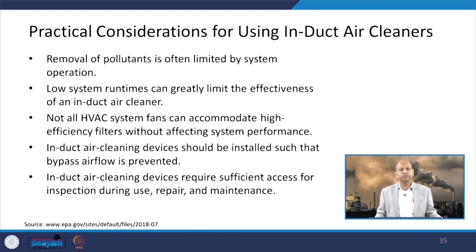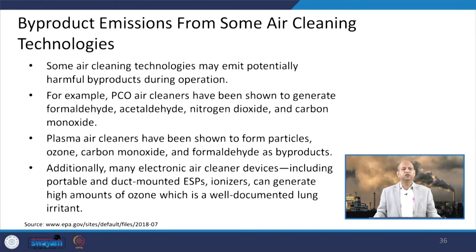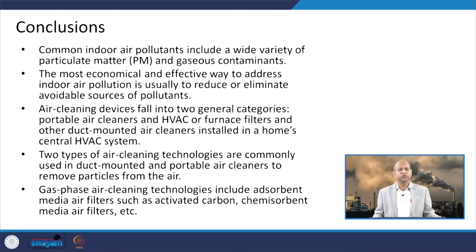Well, induct air cleaning devices should be installed such that bypass airflow is prevented, otherwise efficiency will be greatly reduced. And induct air cleaning devices require sufficient access for inspection during use, repair and maintenance. Otherwise, if we do not have proper access, then some kind of pollution accumulation can occur inside the ducts, etc. Well, the byproduct emissions from some air cleaning technologies can be an issue. As we have seen in PCO, plasma or ozone related devices, if careful handling is not there, then rather than removing the pollutants, they can add other pollutants like formaldehyde and acetaldehyde. They can be generated in PCO technology. So, those things we have to be careful about.